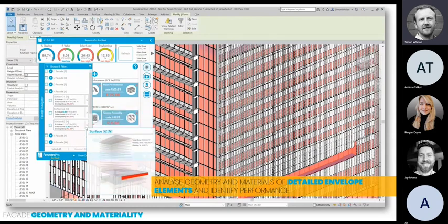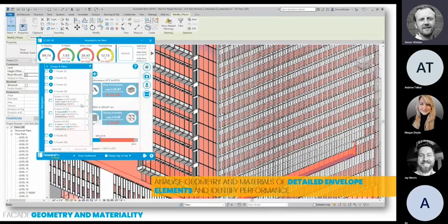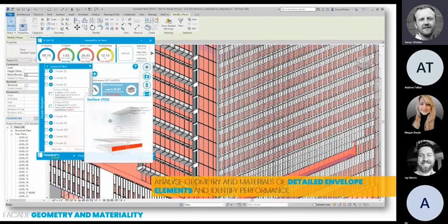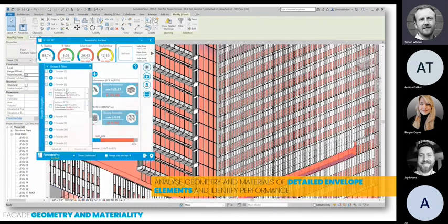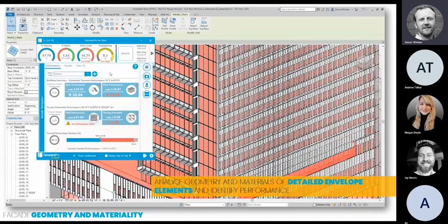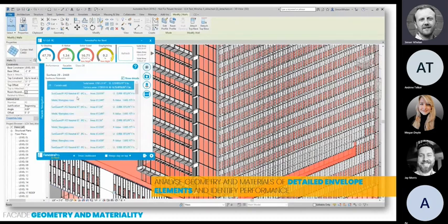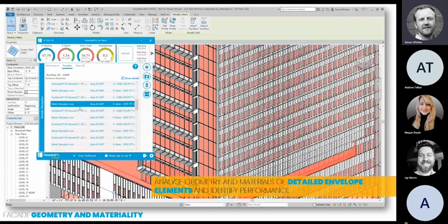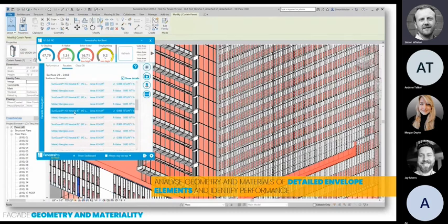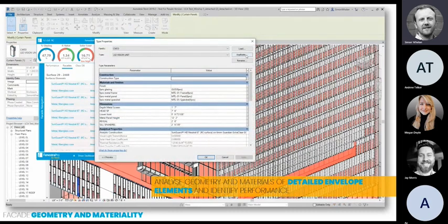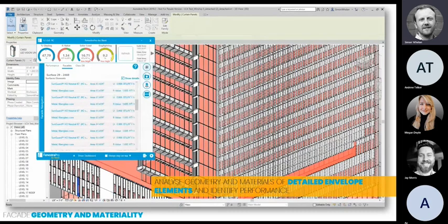We can do little previews where we can select the different spaces and different surfaces that I'm looking at. We can select by orientation. We can select by the story. We could select by just the number of the facade, or indeed we could rename those facades. So rather than facade 2, I can call that Simon's facade or my key facade or whatever. But I can also create facade groups. So I want key facades, and in that key facades group, I'll put in facade 2, 3, 4, 9, and 12, and then every time I select the group, everything will be selected.